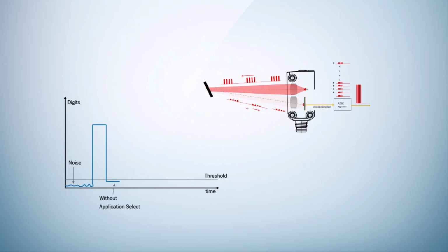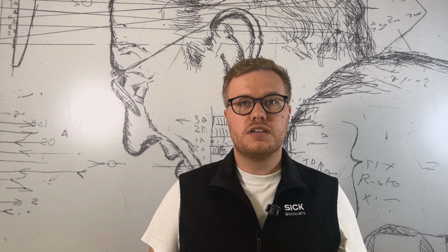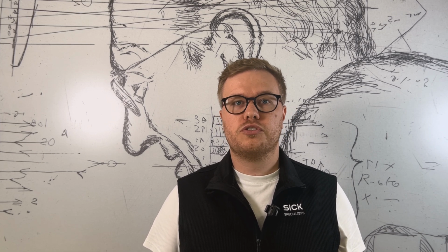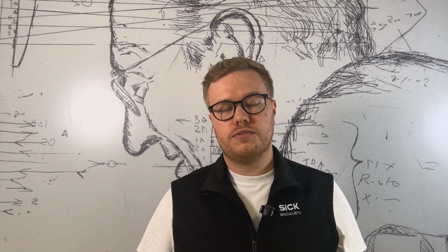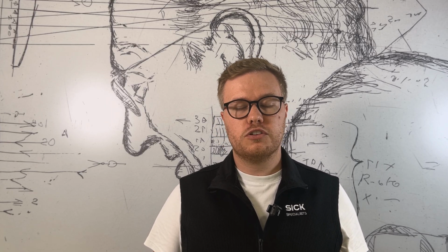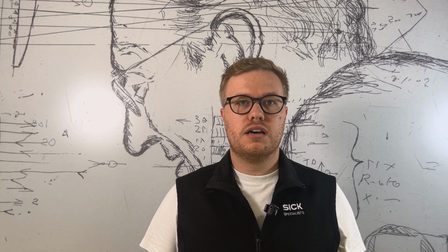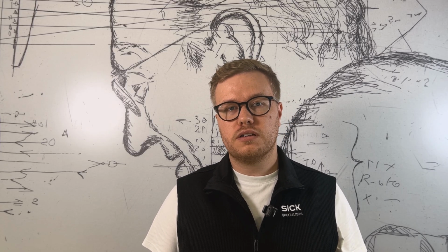The sensor thus becomes more sensitive and can consequently reliably detect objects at greater distance, at an angle, and objects that reflect little to hardly any light. Because the sensor needs more time for accumulation and evaluation, the sensors have a longer response time, which is typically around 15 milliseconds. With the additional ApplicationSelect function, a more robust object detection is achieved that is second to none. The sensors with ApplicationSelect are easier to set up, can be integrated reliably into machines, and allow for a smaller installation situation.